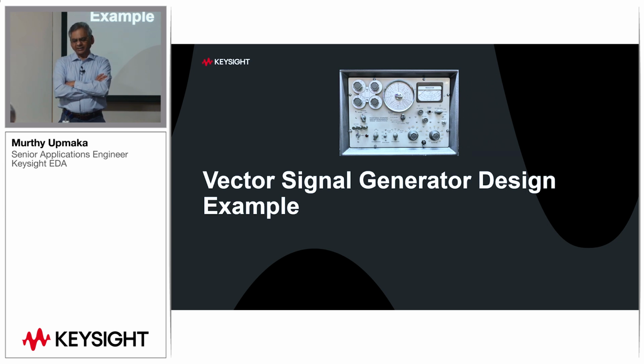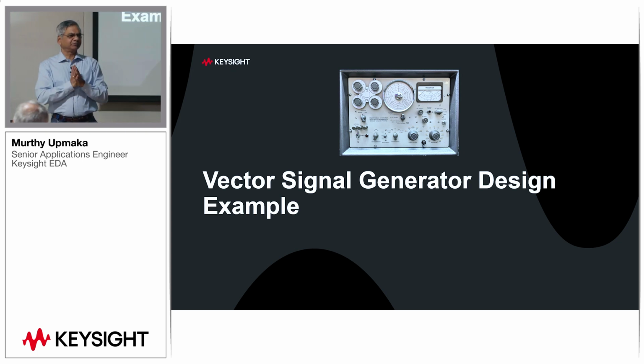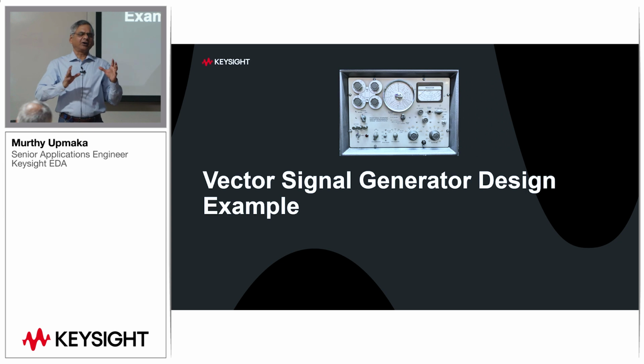Right. Before I go into the amplifier, all the passive linear networks in your system are perfectly characterized with S-parameters. So a Touchstone file is wonderful. It's gold, and if you measure that, you are able to model your part very accurately.